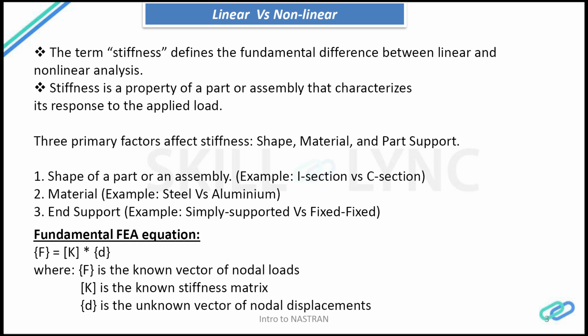because the material plays a very big role in driving the stiffness properties, because we have axial stiffness, which is EA, and then the flexural stiffness, which is EI. That brings into the picture mainly the Young's modulus among all the material properties. An example of the material is steel and aluminum, where steel is 3 times stiffer than aluminum. So the type of material plays a very important role in driving the stiffness of the structure.